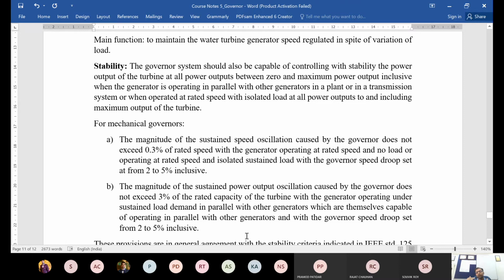You only had your own generator and you just needed to set its frequency, and the operation was simple. But here it is slightly more complex, because if there is a load change, this load will be redistributed amongst all these generators, and some generators will have to increase, some will have to decrease their set point, some by a higher value, some by a lower value. So a lot of combinations are possible. That's why here the norm is slightly less stringent.